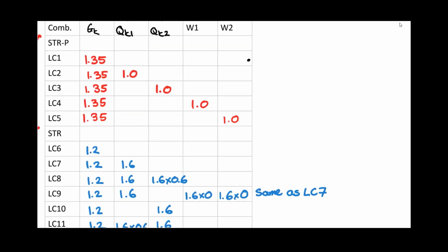So here I've generated all the different load combinations, and firstly what's been done is 1.2 has been set for all the permanent loads. This is when the permanent load makes the loss worse, it makes it higher. This is an unfavorable load combination, and then we'll run through again where we would have all these load combinations again, but with 0.9 instead of 1.2.